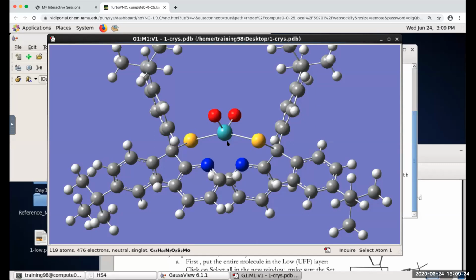But the minute you put molecular mechanics in the mix, you have to be very concerned as to what bonds are drawn, because the atom type that it assigns depends on the bonding. Because remember, with molecular mechanics, it's all about, this is my element and I have it bonded to these atoms with this particular bond order. Okay, so the first thing that you need to do is fix the bonding.